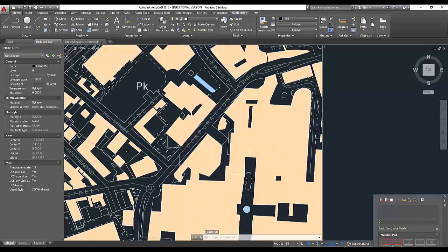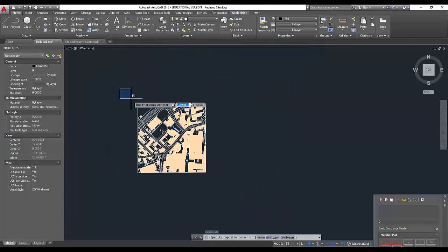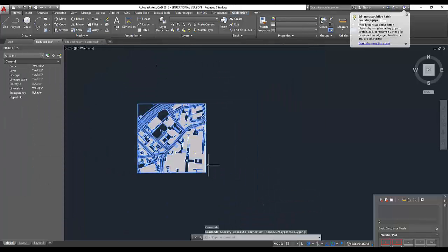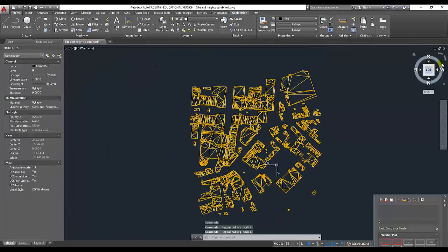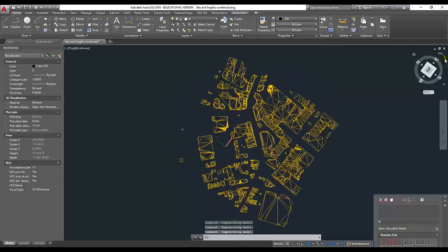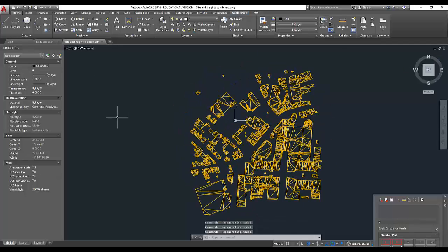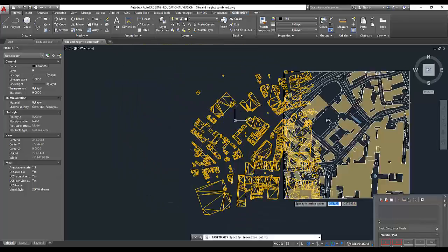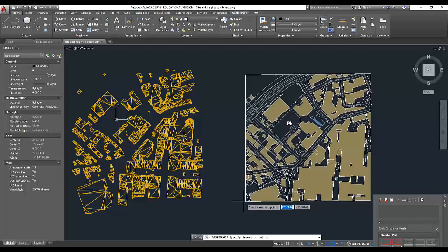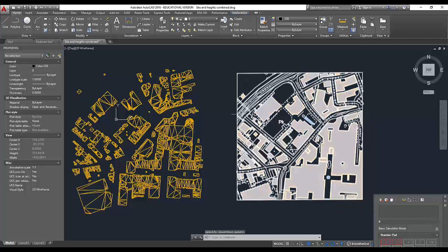Now I put the origin of that slap bang in the center. If I just was to select this, Control C, come into this and Control Shift V. This is going to insert it as a block, and then I'll insert it away from this. So this is all one thing now, not broken up into bits and pieces.